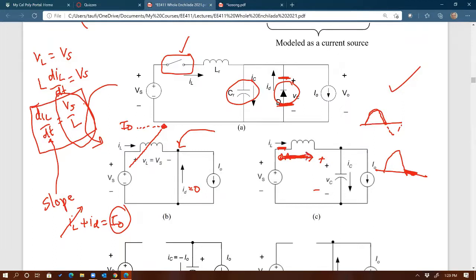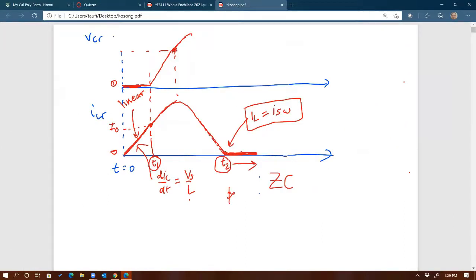But that doesn't mean that the switch is off. I can still have the high pulse into the gate, even though the current is 0. Oh, so what you're referring to when it's on is basically if it's allowed to conduct, if it's going in the right direction. That's correct. Okay, that's what I wanted to clarify. So at this point I can still have the switch on, but right now it's conducting 0 amps at T2, so it's not acting like a short circuit, like an on switch.